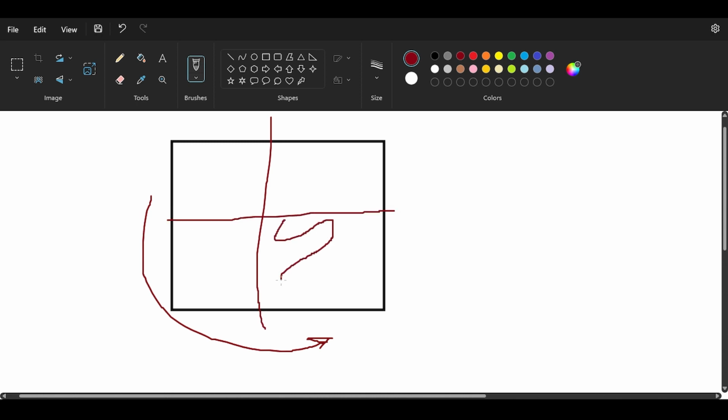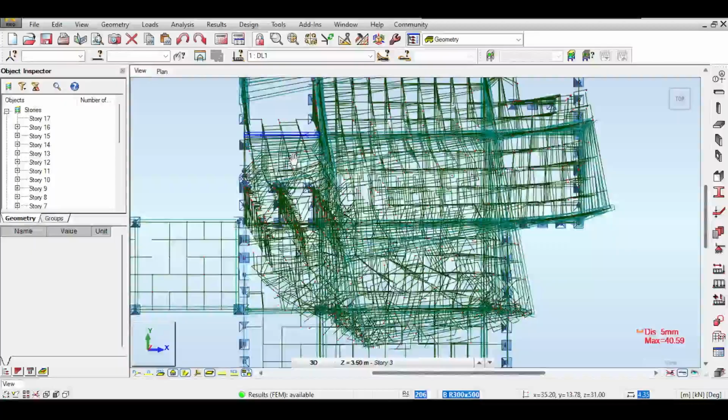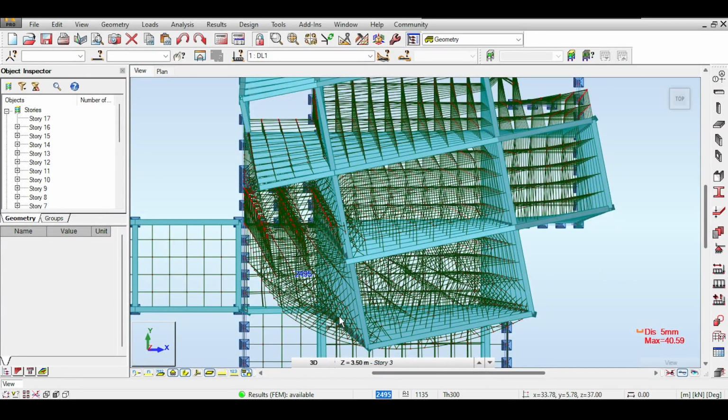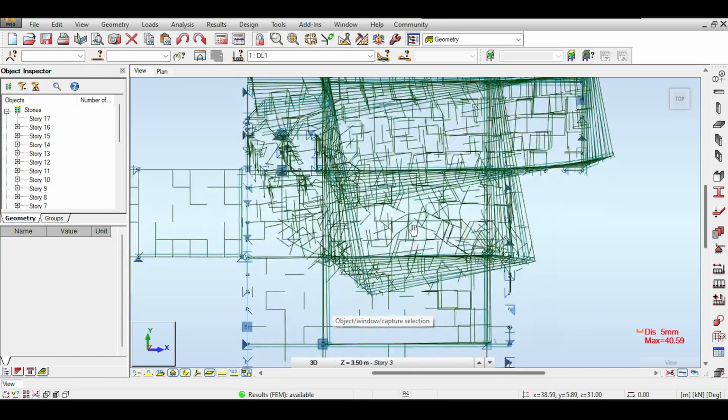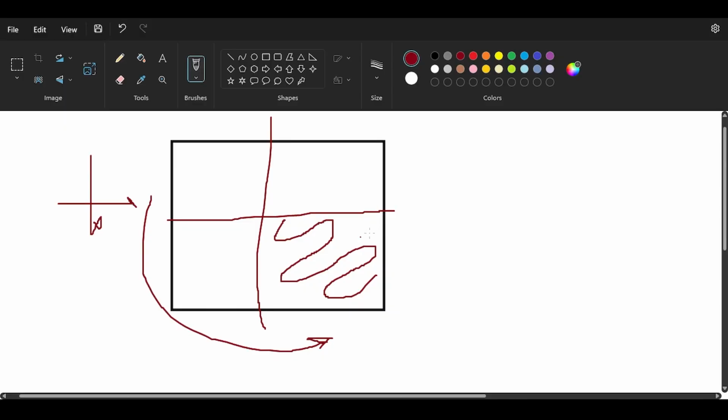So this should be the most effective domain to start with. And then after I start by stiffening this domain, because look, twisting means it goes down, it goes right, you can see it here. If you go to top, you can see the structure both going to the right and going down, albeit with different rates, and that's why the structure is apparently twisting, but it's a real nightmare and I have to think about this. So I'm thinking to add something that stiffens in this direction first of all, and then I will see what I will do with the bottom side.